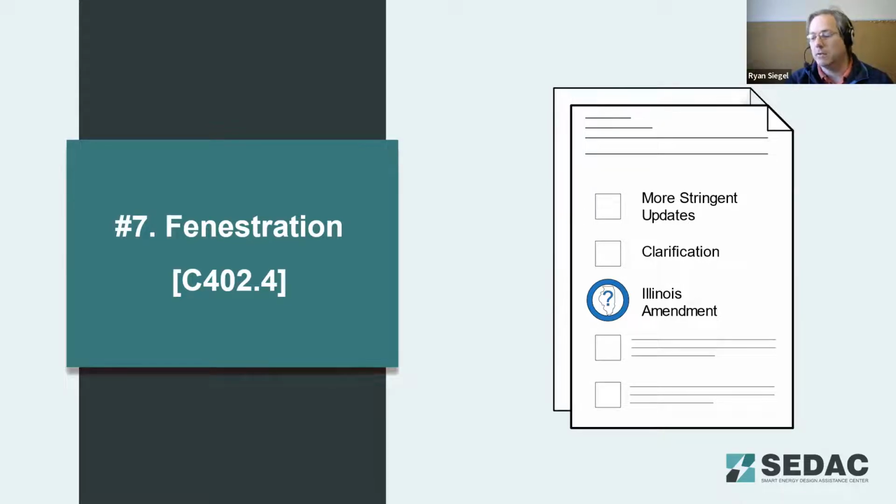Typically, we do see in tapered insulation applications frequently the average is notably above that requirement already, just by the sheer tapering of the insulation as set forth, as far as the minimum all the way up to that maximum. That average is commonly above. But if you do have a smaller low slope roof with tapered insulation, it may be such that you're going to need more than that 1 inch minimum in order to achieve your required R value for that. So good catch on that.